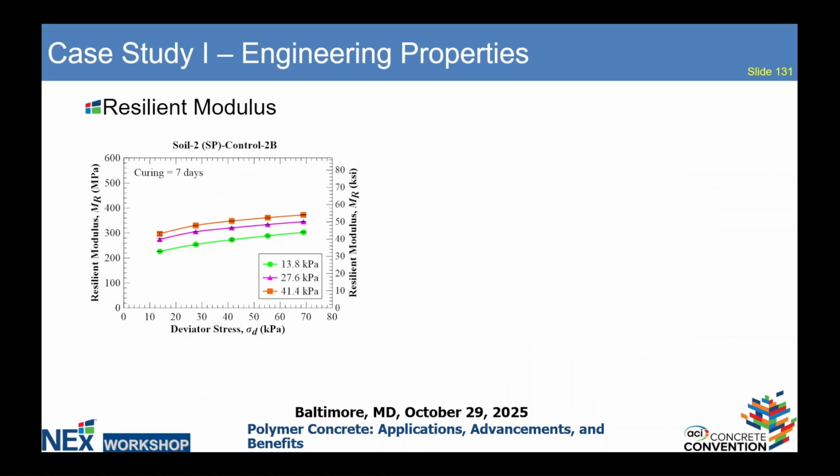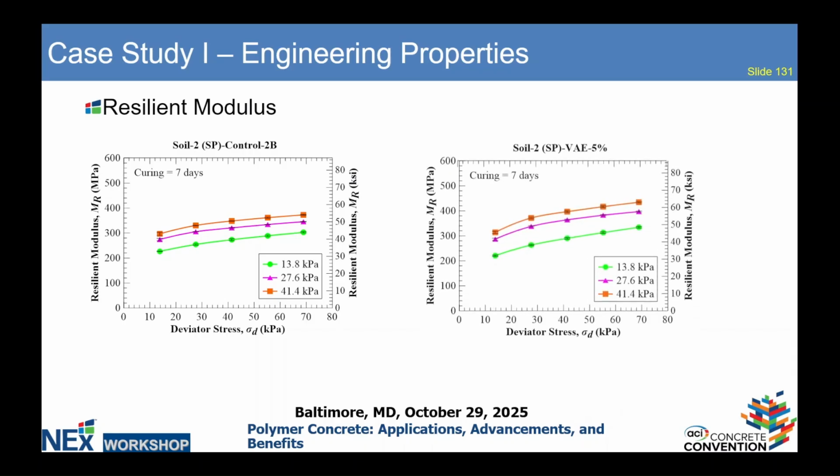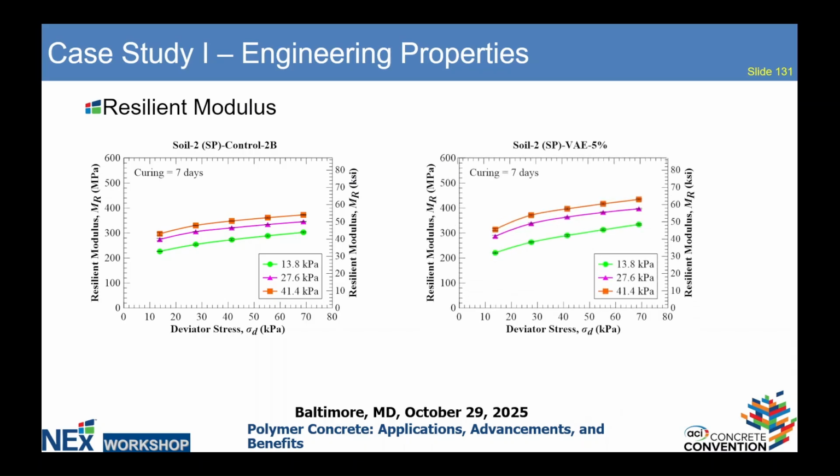And then the parameter for pavement design. Well, some states still haven't used the resilient modulus yet, but there are more and more agencies and DOTs starting to incorporate the pavement ME design into their pavement designs. And here are the interesting results that we found. Even though strength-wise we show a significant strength improvement, for resilient modulus, if you look at this, technically you can say the numbers are increasing, but from a technical perspective, they're basically similar.